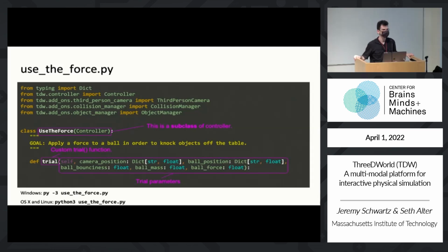Okay. The question is, what's the difference between get_add_physics_object and get_add_object? That's a great question. In some cases, we don't care about the physical nature of the object, such as those chairs floating around in the earlier example. get_add_object just adds the object to the scene and assigns it some default physics values. They're usually wrong. If we care about the physics state, get_add_physics_object will assign physics values in addition to everything else.